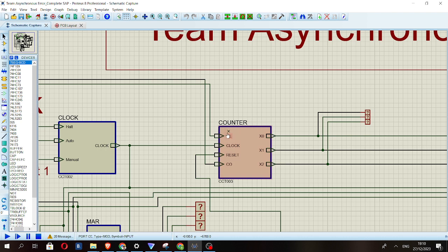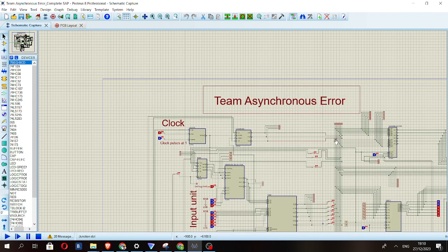This was done because the CE operation itself does not cause any bus contention issues, so it can be placed wherever we want. It does not need to be a micro instruction in and of itself. So that enabled us to have just 5 micro instructions instead of 6.